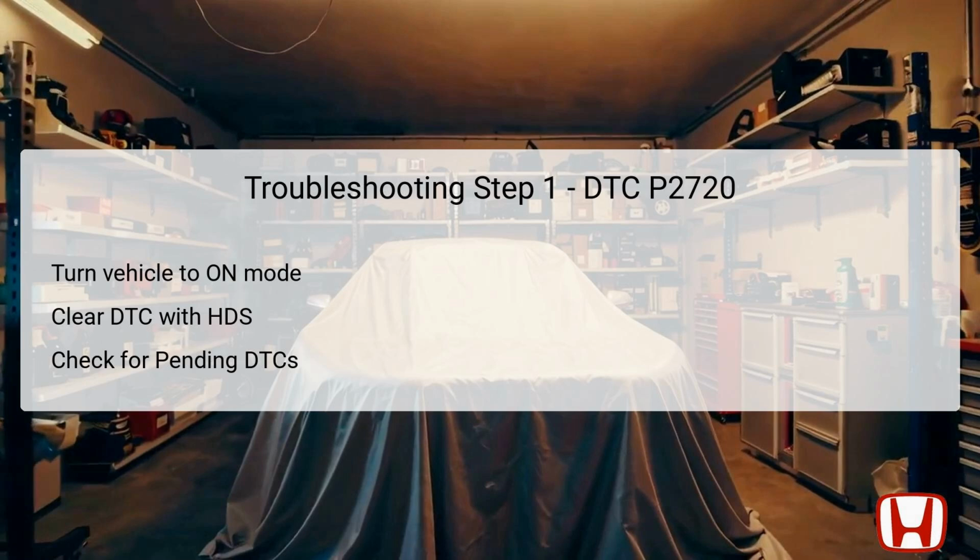Following this, it is essential to check for both pending DTCs and confirmed DTCs using the HDS. The outcome at this stage will guide the technician in determining what actions to take next. If DTC P2720 reappears, proceed to troubleshoot further, as this indicates a consistent issue. If it doesn't, the problem might be intermittent, and may require a more detailed inspection of electrical connections related to the solenoid and the PCM.